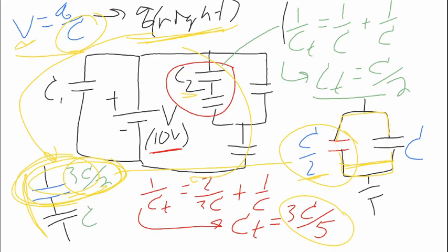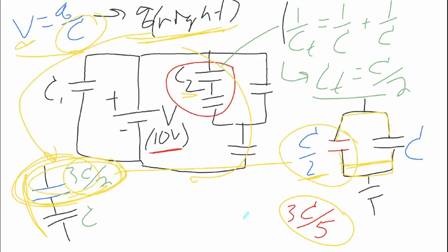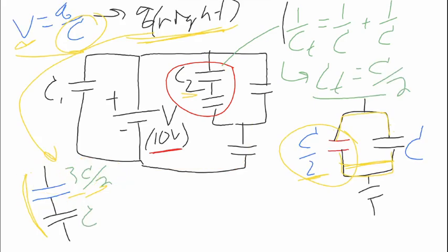And so I would do Q equals V on C. Oops, that was supposed to be an erase. Okay. I've done a lot of this out loud, so let me take a second to do an actual calculation here. I've got V equals Q on C is what we're using, and we're using the charge on the right-hand side and this capacitance. So that would give us the voltage as being Q through the right over 3C on 2.